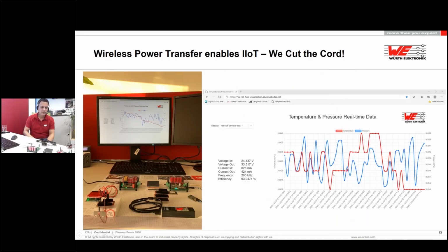If I'm doing that, I'm able to create data. This data will be created from the temperature sensor. The temperature sensor is sending the data in-band over the UART, over the wireless proprietary protocol to the Wi-Fi module. The Wi-Fi module is sending this, for example, to a dashboard. And then you can see this curve.